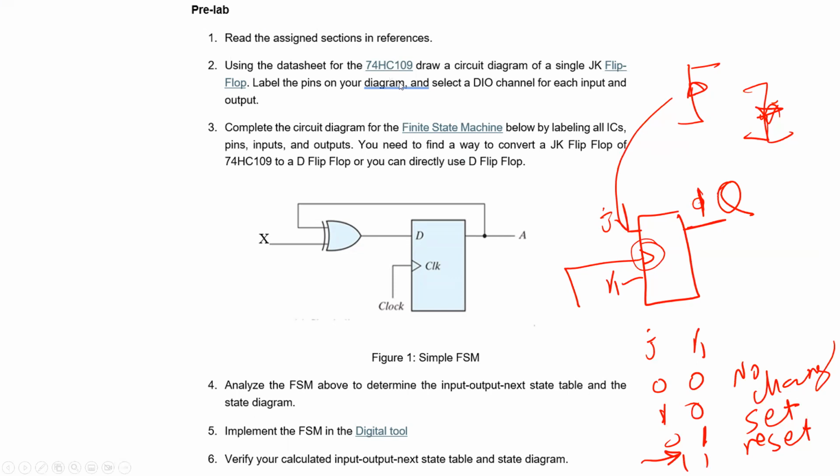You will see, we will explore this chip. You will see this chip has a reset, and we'll see that right now. Also, we are going to see if it is positive edge or negative edge. But there is a small difference, as you will explore. This is the normal JK flip-flop. However, as you will see right now, this flip-flop has J and K prime.